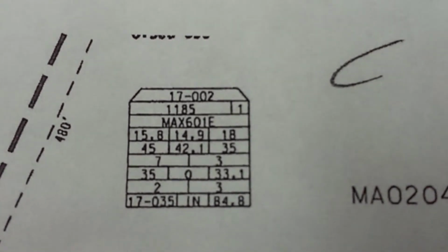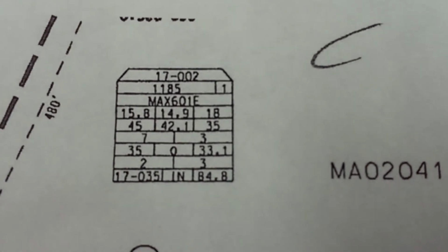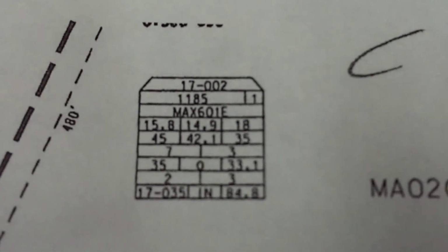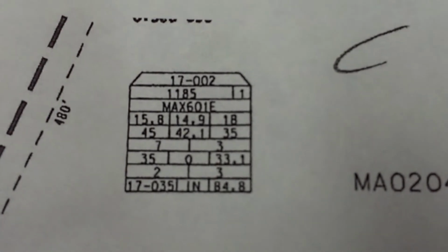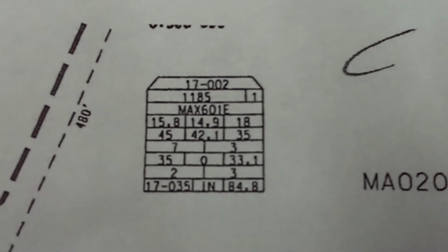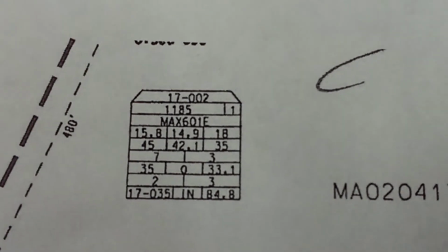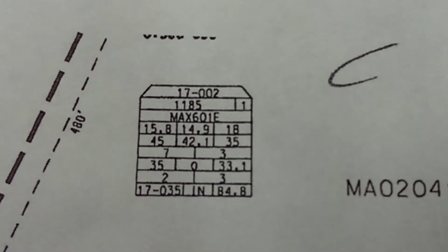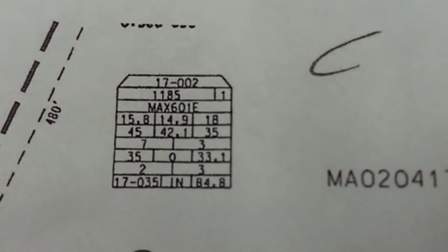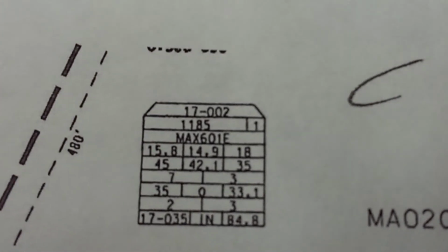The next numbers below that, 15.8, 14.9, and 18, right? Those are my input levels at my base frequencies. Frequencies are 3, 58, and 108, actually 107. That's unique, specific to the area you're working in. So you need to know this because, all right, 15.8, that's my low frequency. That's usually channel 3, all right? If we were balancing this, we would need to know that information. You're not going to get into that, but it's good to know if you see that.